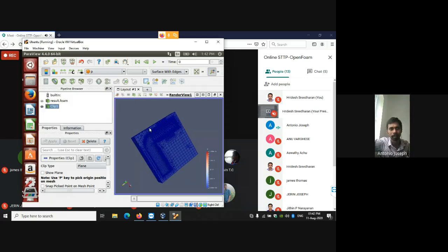there are a lot of spaces outside that cylinder region which are not refined. These are the regions where it's not refined, outside the cylinder region. If I had given the command as outside the cylinder, then those portions would be refined. In some situations we come across this because we want to refine a region which is outside that particular area.